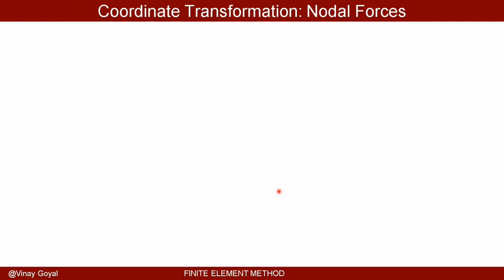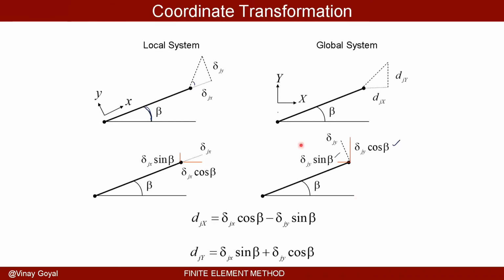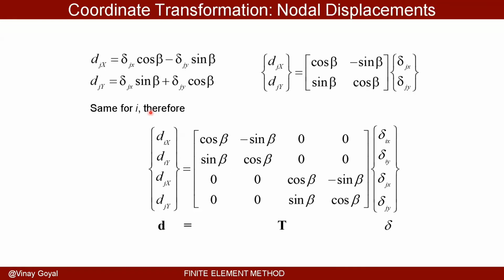So I demonstrated to you that D bold, the deflections in the global orientation system for the two nodes, is equal to this transformation matrix. And beta, again, is the angle of that truss relative to x in the global coordinate system. That beta is going to be known for every truss. That matrix is fully known. Times the deflections in the local orientation system to the bar.